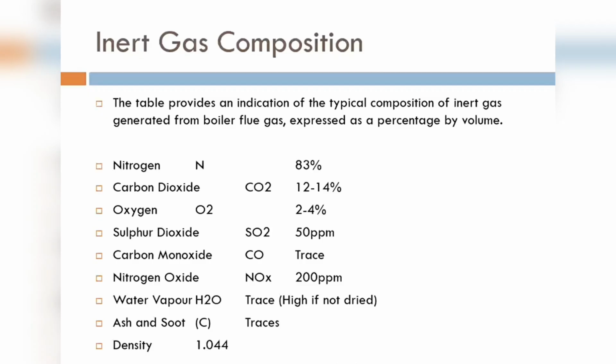But when you are using a nitrogen generator for generating nitrogen, which is used on the chemical tankers, we don't use the boiler uptake, boiler exhaust. That boiler exhaust will react because there are other gases also. But when we are putting pure nitrogen, 99% nitrogen, in the cargo tank, this is a special generator. We cannot use the boiler exhaust for this purpose, because there are other gases also, other solid particles also, which might react with the chemical. You are talking about chemical tanker, right?